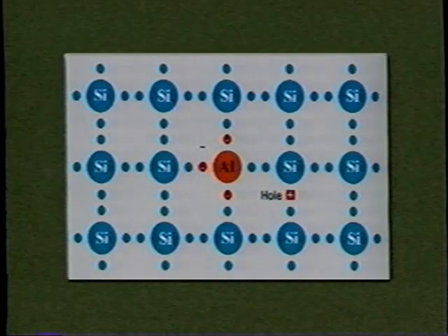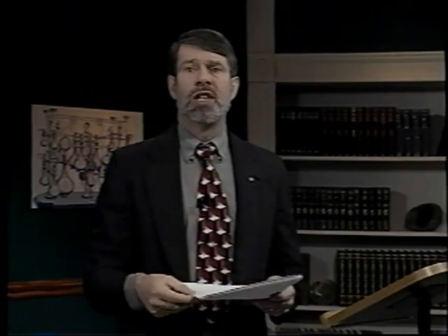By adding a small fraction of aluminum atoms to a silicon crystal, then, you're adding a controlled number of positively charged holes which can move around the crystal. And the result is a p-type semiconductor. Now, one important point: N and p-type semiconductors in and of themselves alone are just lousy conductors of electricity. They don't really have any significant use by themselves. They only have about 1 in a million atoms in these cases that are contributing a mobile charge carrier to carry electricity. So they have no special use in electrical circuits.